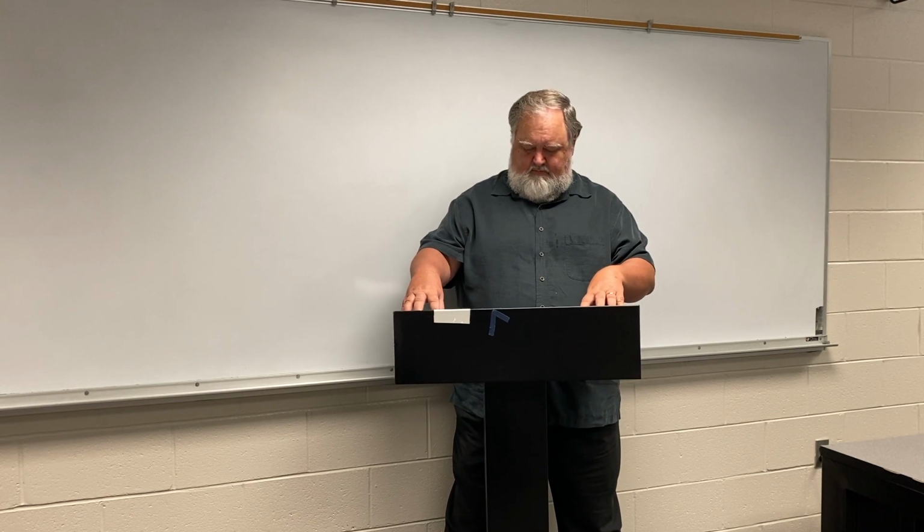So that's called a live load. Anytime the load can shift, because as you walk, you have as much as 250 or 500 if you really hop and jump, yes, as little as nothing. So it's a shifting load. A dead load would be like this, whatever this thing is here, podium. It doesn't shift until I lean on it, but it has a weight that isn't going to change.